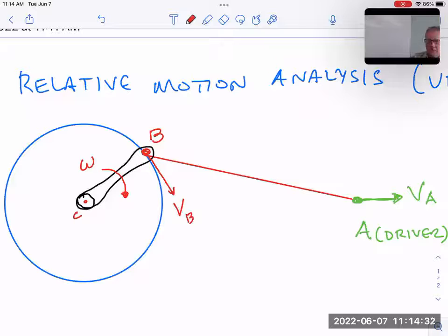And notice, how did I want to draw that? 90 degrees, that's exactly right. Thank you for reading my small mind, Thomas. That angle right there is 90 degrees. And so the velocity is always perpendicular to the circle it's on. Earlier in this class, we studied that it's on a circle always, even if it's traveling in some random motion. It's just that the radius of the circle is constantly changing, but it's constantly a circle. So that's actually the velocity of B.